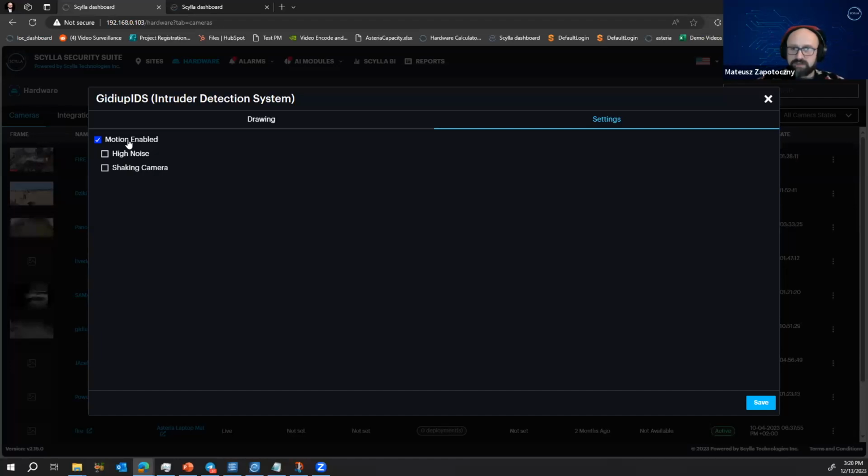We have something which is called eagle eye. It works like this. You have the image of the camera, and the first module that it's working on it, it's looking for a motion. If there is a motion in some region, it will make a smaller stream from this region, and it will put it inside the AI module. This way, the AI can analyze the full resolution of the camera, even 4K, even higher than 4K, but it's not overwhelmed by the data because it's analyzing only small fragments of it. And you can still connect the full resolution. So this is the huge benefit of it.